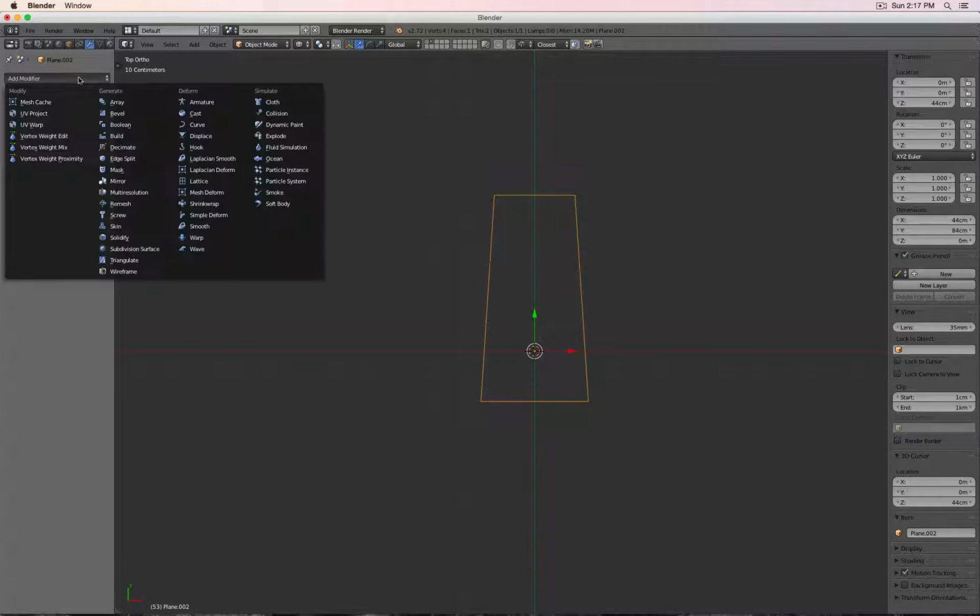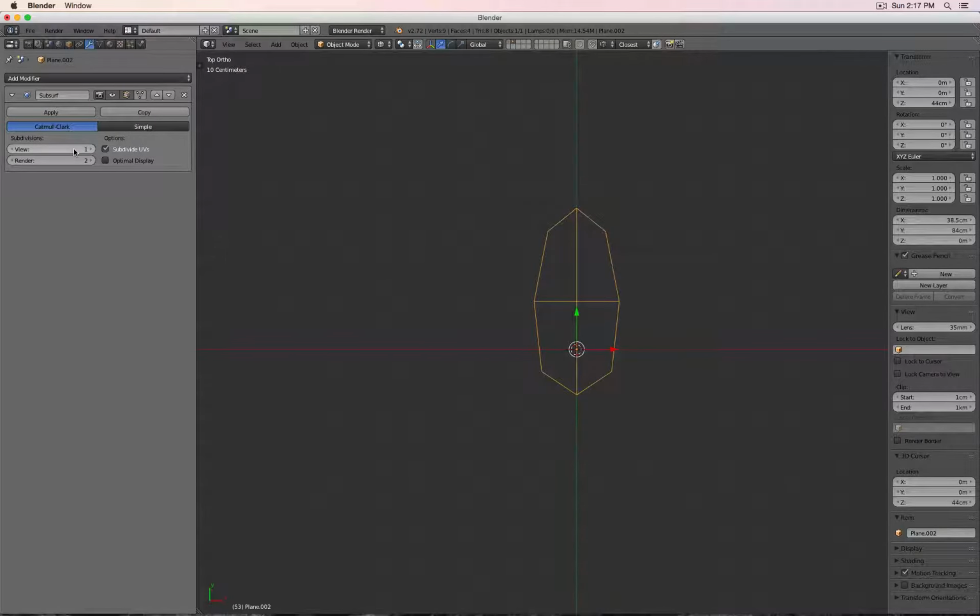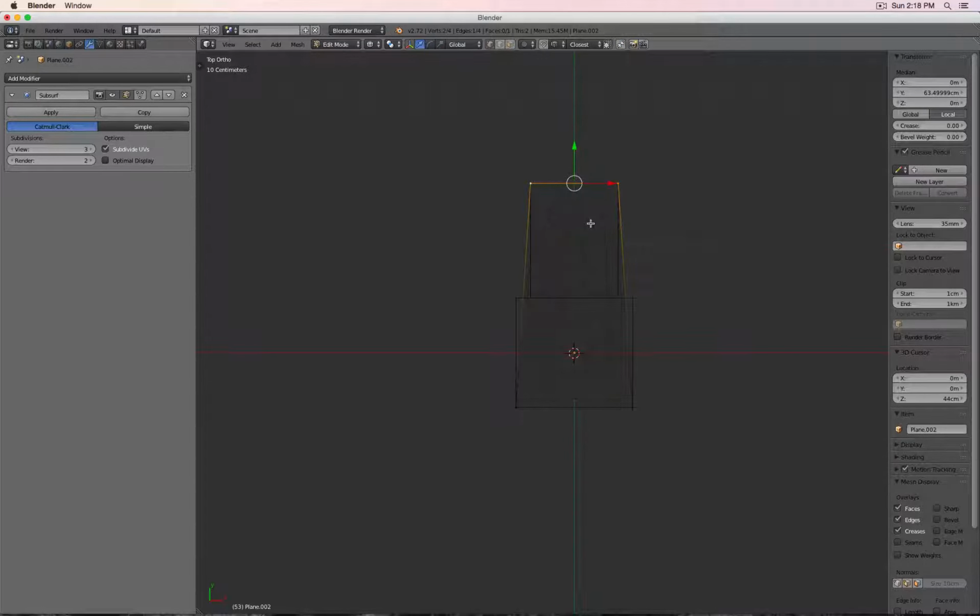And for example, let's give this one a subdivision surface modifier. Maybe let's say 2. Now this is very egg-like, and that's not really the shell or shape I need. So I go into edit mode, add maybe 2 loop cuts here. S and X, scale them apart. 2 loop cuts here. And now here I can't scale them, because if I would S and X scale them, you would see how this changes the shape.